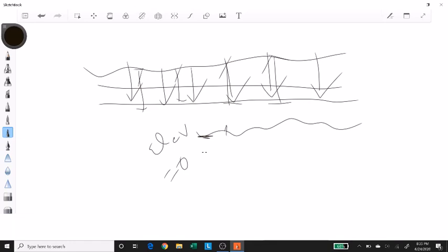Then when I find out the heights of different points, they will be from this reference line, which has a height of 0. And whatever height difference between these, these points will have values greater than 0 if they are above the point, and if they are below the line, they would have elevations in negative. And usually this reference is used as a conventional one, which is usually the mean sea level.